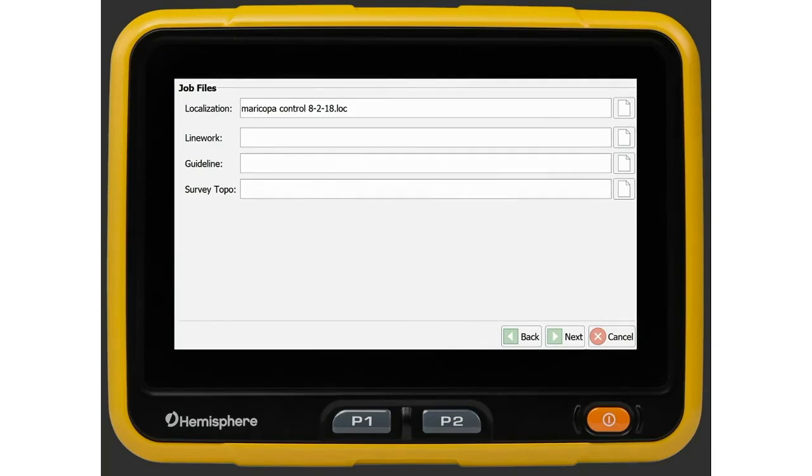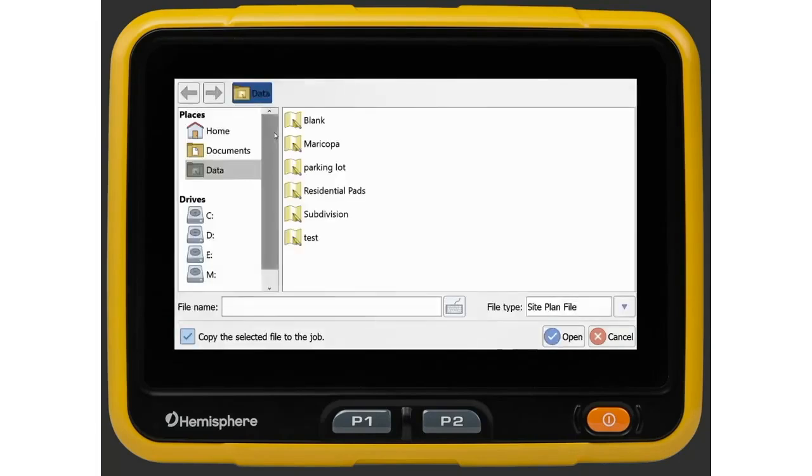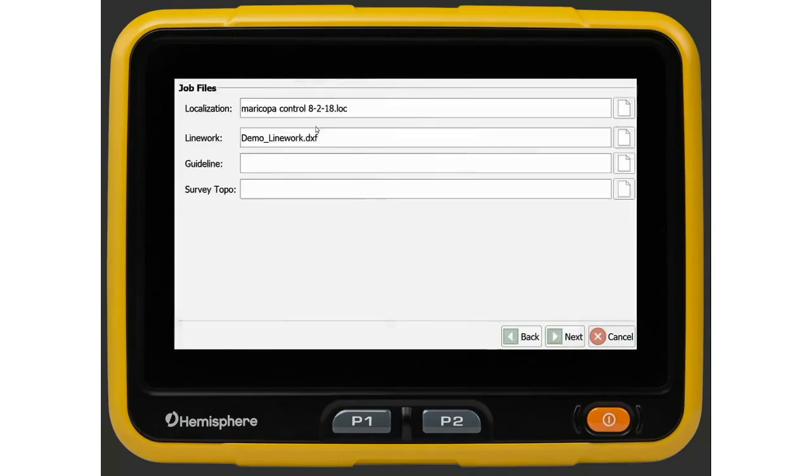We also have the capability to bring in a calibration file from Trimble Construction or export the point data needed from TalkOn, making it easier for customers with mixed fleets. The second file needed is line work. This is the lines you see in plan views and are obtained from the project engineer or model builder. We accept DXF or DWG.